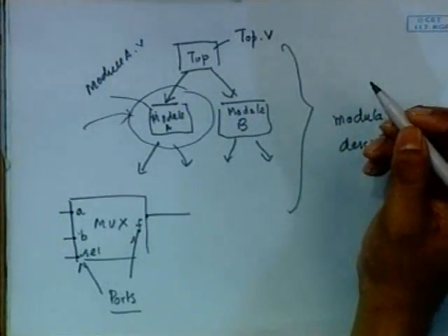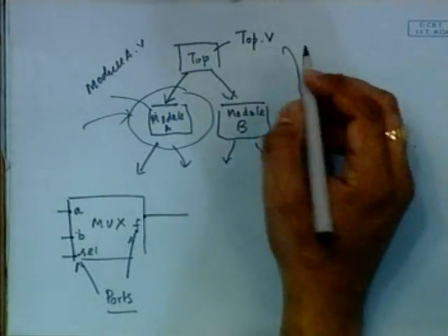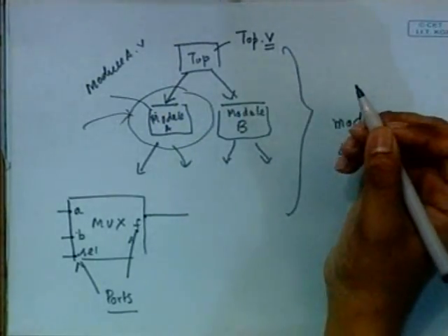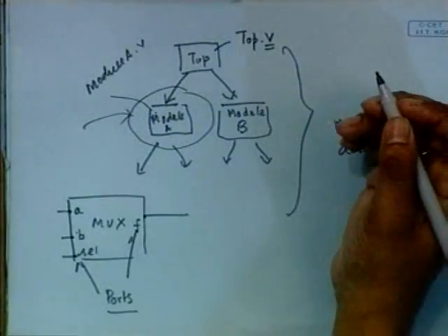When you go to your laboratory, for example, for doing experiments, essentially we will be using a Linux operating system or a Solaris operating system. So you have to write separate files, and in all of these files you use an extension of .v, and then you use the Verilog compiler to simulate your design. You compile your code, that is, you check whether there are any syntactical errors, and then you check whether the output that you obtain is the desirable output or not.